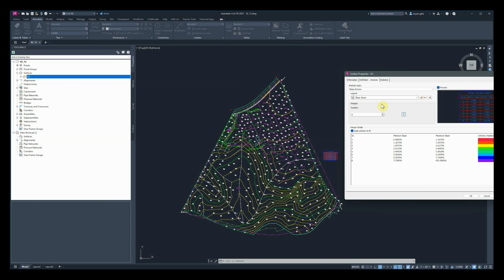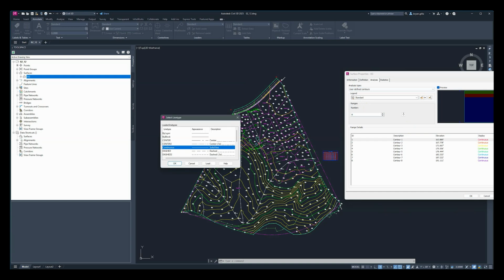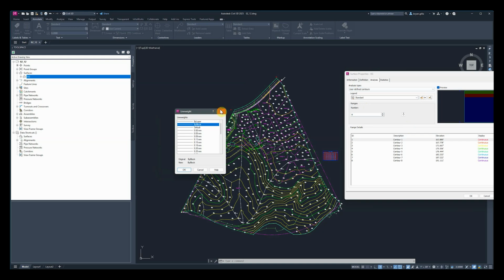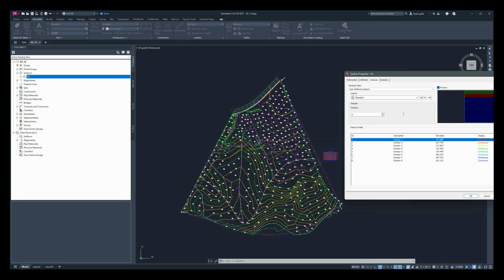After that, let's go to our user-defined contours. Again, 8. Run our analysis on that to generate it. There we go. Here's our preview loaded up. Again, this one, because they're contours, we're going to have the option to not just change color, but change our line types and our line weights for each category if we needed to, or each class.